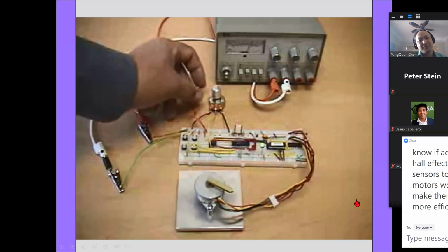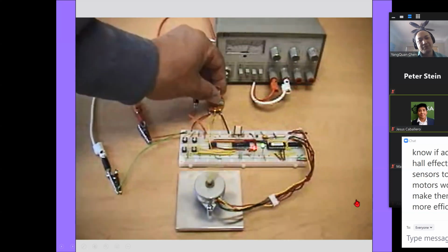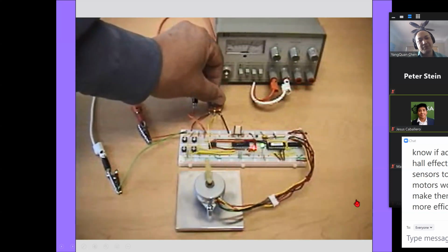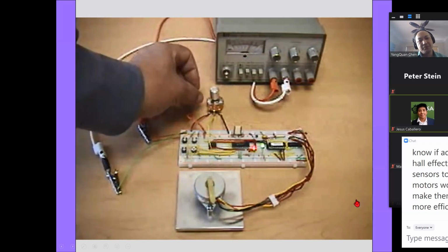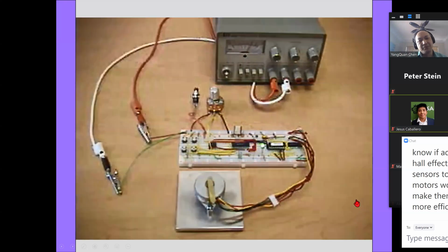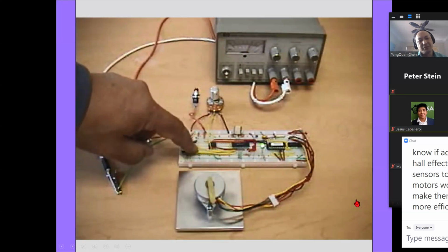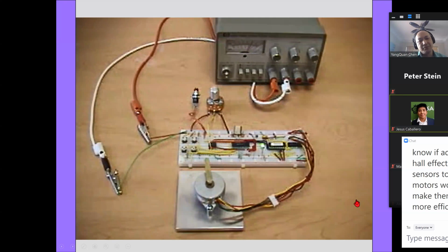If we go back into speed mode and move to a slower speed, and again enter position mode, now the motor can track the positions starting from 0 speed. Again, to move a stepper motor at a fast speed, you have to gradually accelerate to get to that speed. You can't start at that speed immediately.